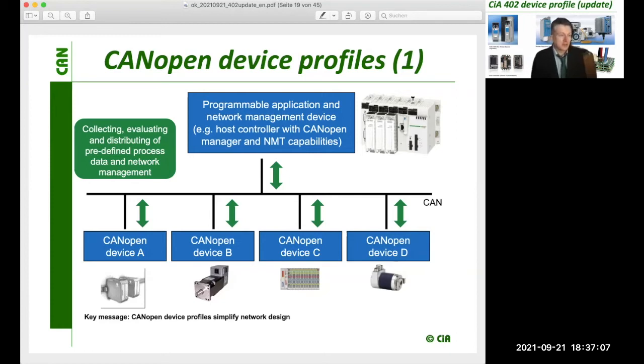There are no such parameters for other CANopen device profiles, and thus it allows you also using PDO mapping with this data, creating devices which you could simply and easily configure in one specific network.